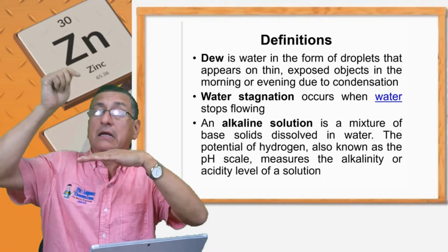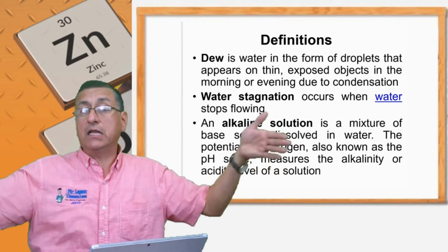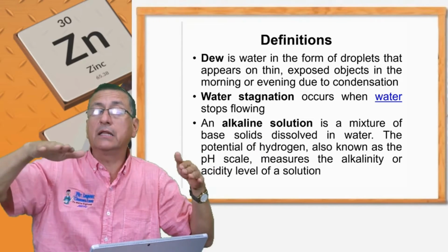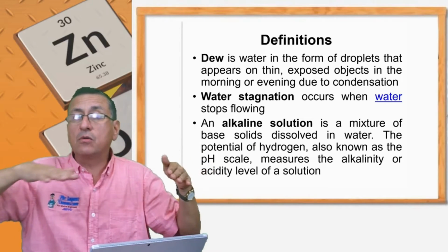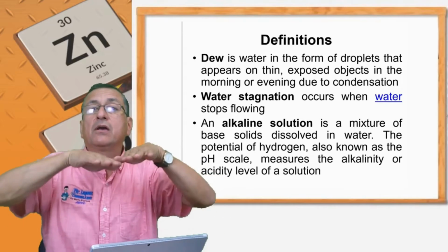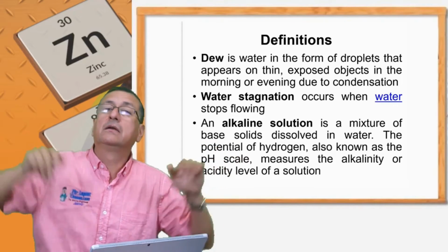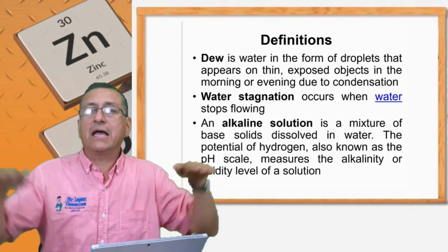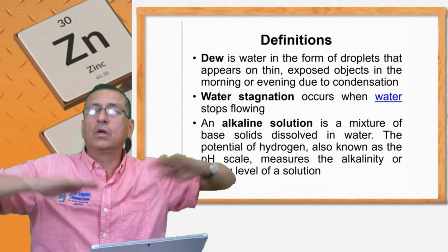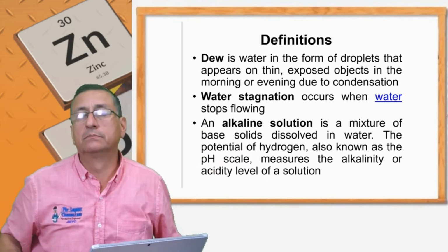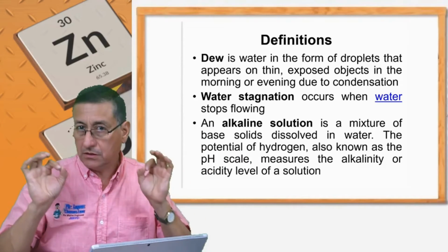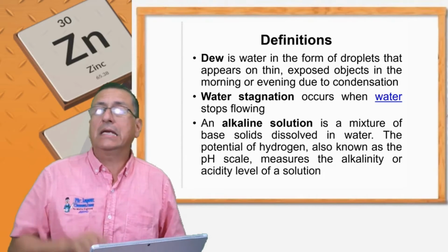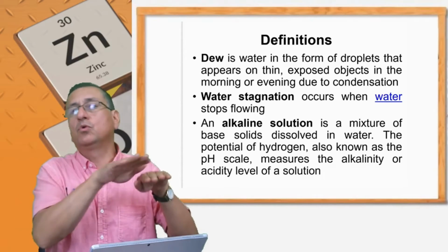When you have a leak, I have the fuel tank in aluminum, and I have a leak of water, drops, and that water is accumulated on the surface of the tank because the tank is flat, it's not inclined. For that reason, always design those metallic tanks with a little inclination to avoid stagnant water. That's another important factor at the moment that you design. Incline the surface all the time to drain water.